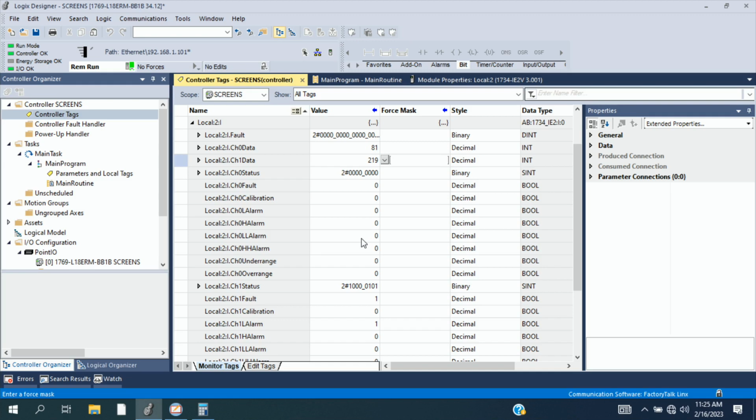Then on the low side of the alarm limits, I guess we'll find out where they were set. I think it was 70. There's the low alarm just went off here, it's at 68. And if we drop below 65, we should then also see the low low alarm triggered over here. So those are bits that we can use inside of our program to do whatever you want. They're programmable. So if this was a pressure thing controlling an air compressor, we could turn on the compressor if the pressure drops below a certain point, and then turn off the compressor once it gets to the high alarm. Those are just some good examples of what these alarms could do inside of our programs. So that's a pretty good deal.